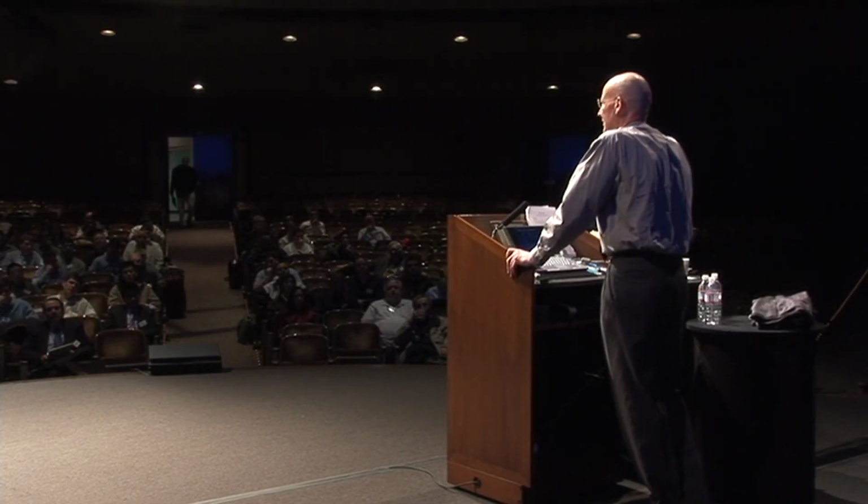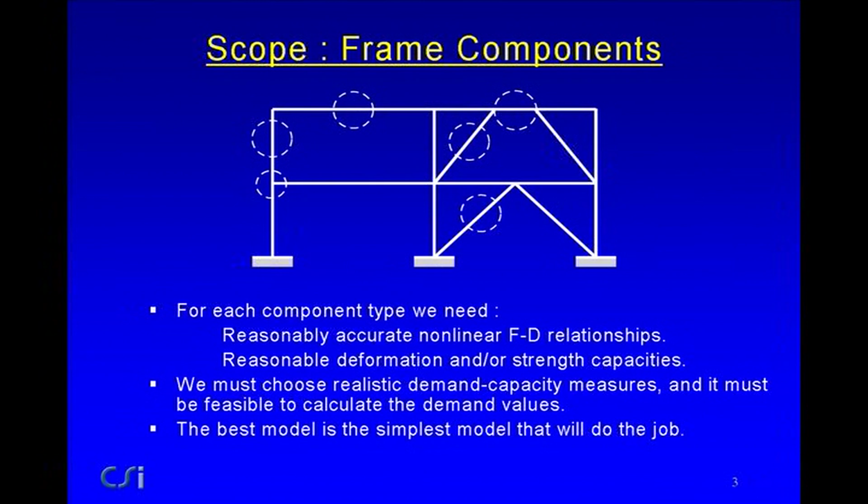We'll never know the exact ductile capacity of a plastic hinge. We've got to make some reasonable estimate of what it's going to be. And again, we have, or should have, factors of safety to cover any uncertainty.